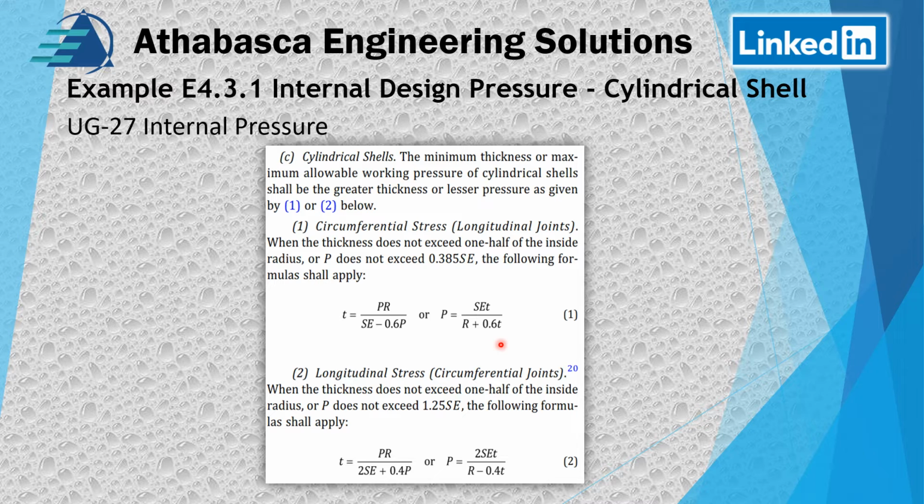It's interesting because the software will let you select your components and it will figure out your weakest link. So you calculate the thickness you need, and you go back. Software like Compress will go in and put your calculated thickness in there, and then figure out where your pressures are for the other components. And this is one of the reasons why they have these two arranged this way.